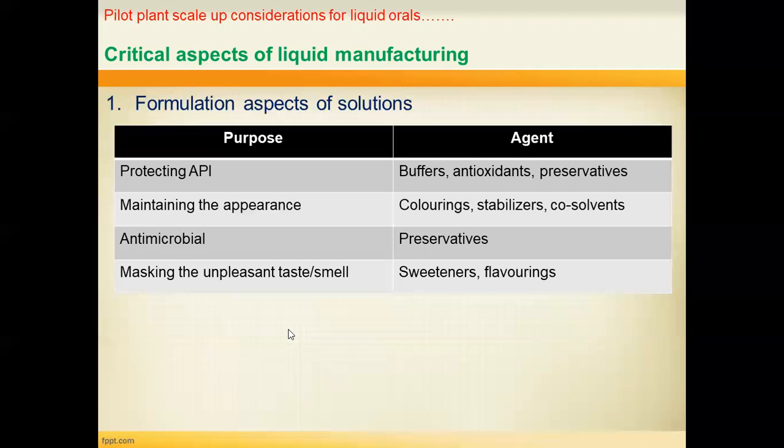In the scale up process, various parameters matter: tank selection is very important, then the mixing should be proper, then the dispersion, meaning what shear forces are used to make the dispersion, and the filtration and clarification. All should be free from contaminants, dust particles, or anything else.